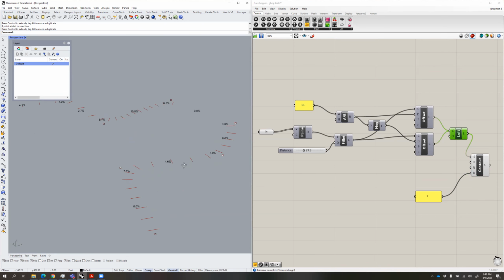So this is one thing I sometimes do: I like to just model the path abstractly using a basic center line, and then set that onto the landscape, and then just have the Grasshopper tool cut contours from that. And then I just simply take these graded path lines and connect it back to existing grade. And that's a very simple way that you can grade a walk in Grasshopper.